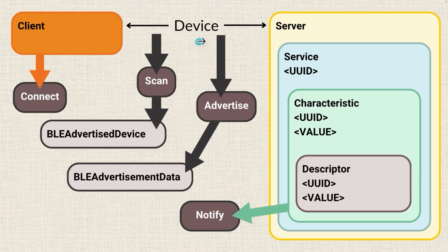If you recall, our device is what started the advertising. So we said BLE device start advertising. So this whole advertising thing is coming at the device level. And what we can do is define some of the advertisement data that we put out in the wild. There's a couple different types of advertisement data that we can specify. We can say, hey, always show this stuff. And then we could say, only show this stuff if somebody's asking for it or actively scanning for it. So there's some different stuff we can specify here.